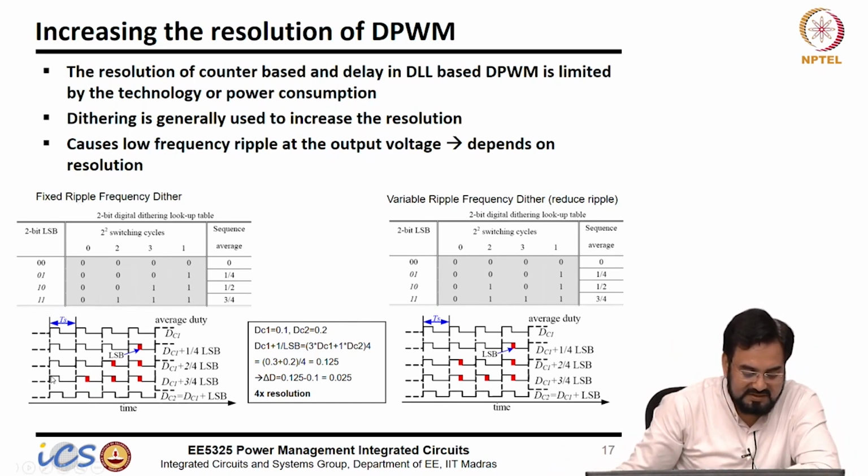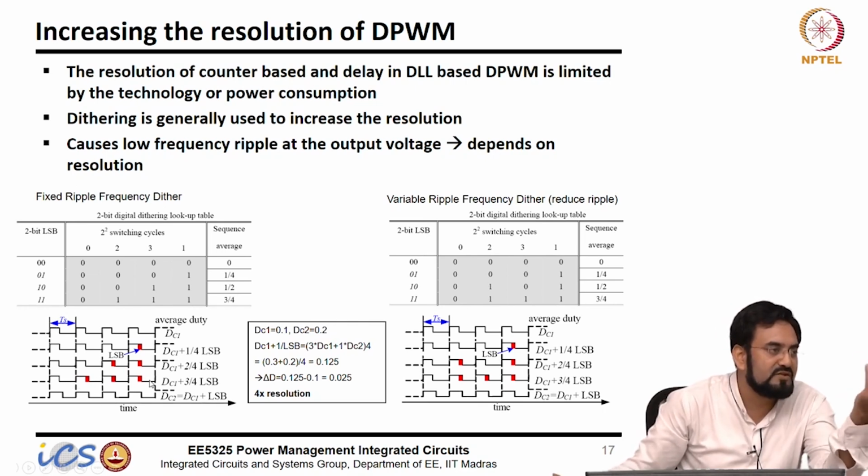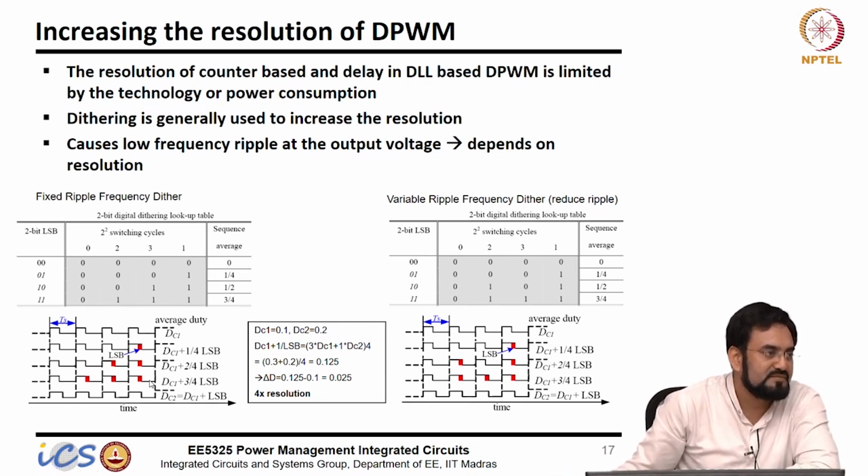When I say dithering frequency, so this is one duty cycle and these three cycles are, let's say, different duty cycles. So on an average, each cycle may have the same frequency, but if you look at another tone, this is your dithering frequency, which means one cycle of this and three cycles of this. So it will be looking like 1/4 of your PWM, correct?